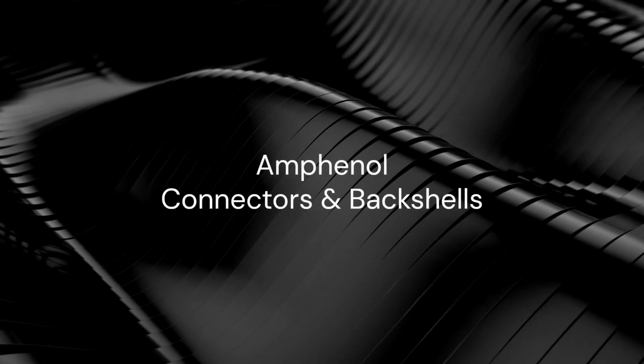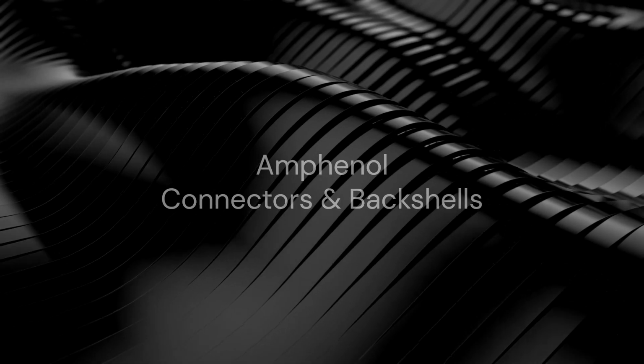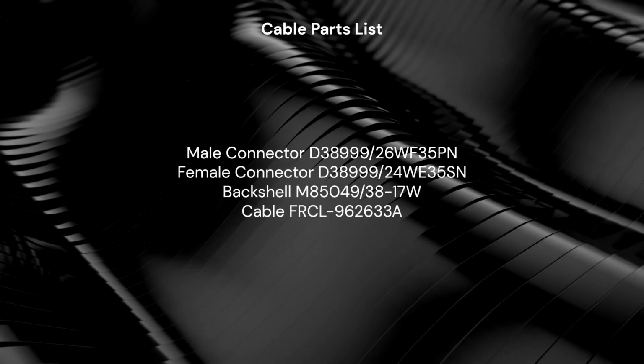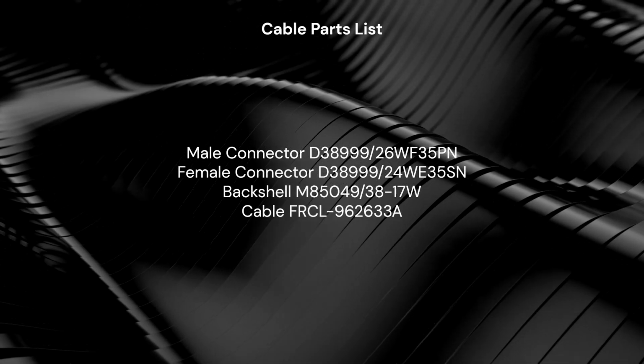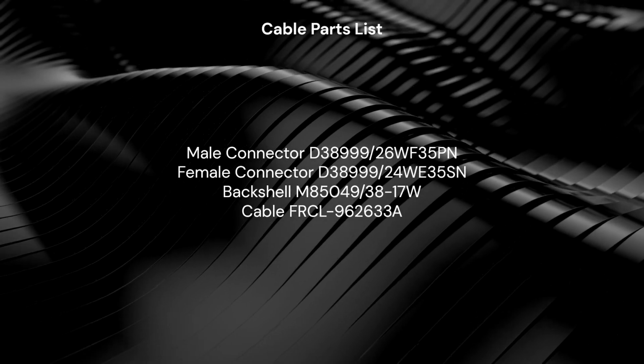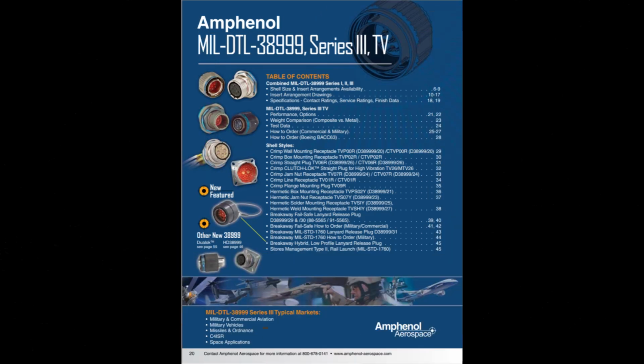In this video, we'll walk through a practical problem involving a cable assembly parts list. Initially, the list contains an error that prevents us from building the cable correctly. Together, we'll identify and fix the issue, ensuring the parts list is accurate and complete. Along the way, you'll gain hands-on experience using Amphenol catalogs to construct valid part numbers tailored to your application.